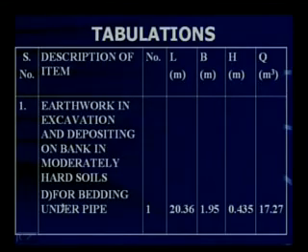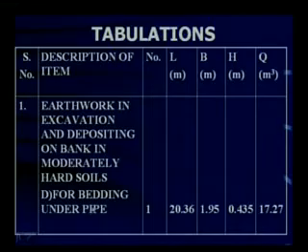Here it is. The last one is earthwork in excavation and deposition on bank in moderately hard soils. There are different types of soils, but when we make an estimate, we assume that the soil is sufficiently hard, because excavation in a hard soil will cost us slightly more. So when the estimate is slightly more, it doesn't matter for us, right? So for safety, we assume that the soil is a hard soil. So this is the last item in the excavation part.